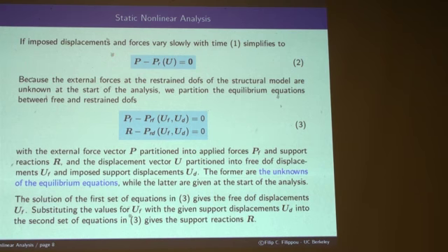I am only going to work with the equations at the free DOFs. Right? There is no point in carrying these equations around because obviously I have as many unknowns R as I have equations. So if you see a textbook in linear analysis that carries this stuff around, you can toss it in the garbage can, as far as I'm concerned. Right? All they do is inflate the size of the problem.